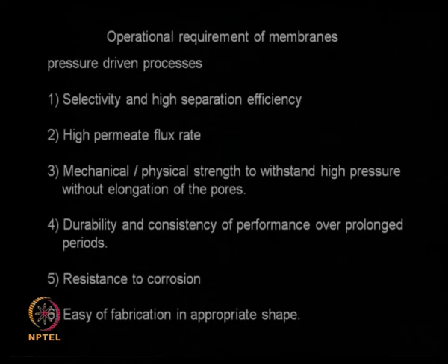There are many operational requirements in a membrane process, so you need to keep all those points in mind. We want to have very good selectivity, we want to have high separation efficiency, so this is the fundamental point. We want to have a high permeate flux rate, that means the rate of filtration has to be very good. The membrane should have good mechanical and physical strength to withstand the high pressure. Continuously you are operating at such high pressure, so your mechanical strength should be quite high. The pores should not get elongated because you are continuously applying a mechanical force.